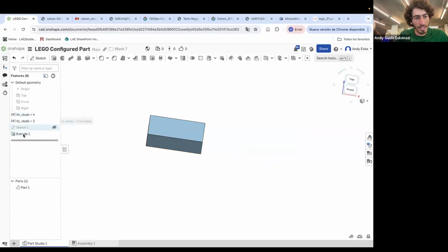It's important to note that whenever you're creating variables, that is the very first thing that you create. I can also move it behind, but you see, it's gonna give me an error because it's not gonna recognize the variable. I did the sketch, and then I'm referencing a variable that comes afterwards. You have to always bring it to the top. There we go, like that.